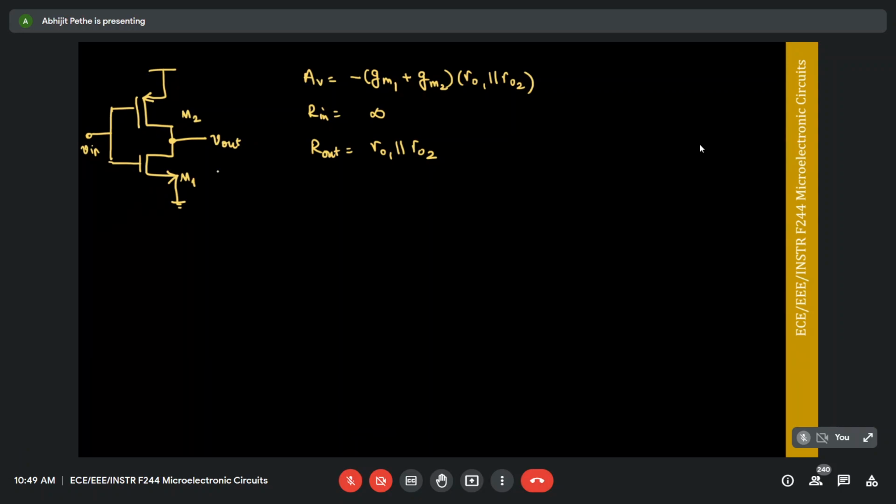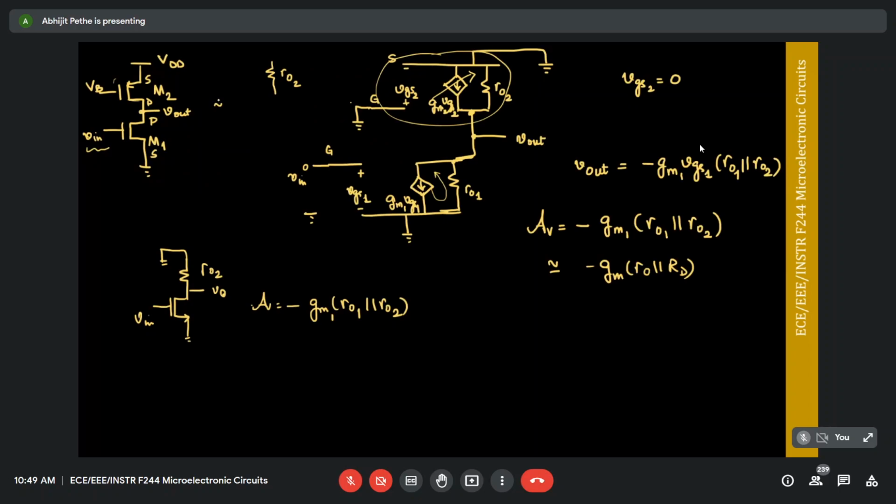So if you look at it, the only difference we've made is that we have connected the input signal to both the PMOS and the NMOS. So again, remember how the common source works. The common source topology works because an input voltage is converted to a drain current, which flows through an output resistance, leading to a gain, right? So in the previous case, when I connected my input voltage, only M1 was converting Vn to a current, right?